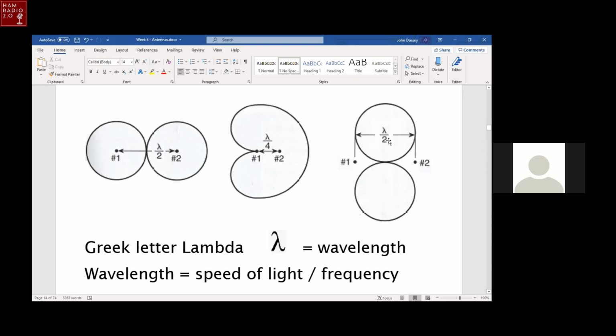That's how you can have a fixed quarter wave vertical array and switch their pattern by changing the phasing of how you feed them. What is the polarization of these? They're all vertical. Yes, they're quarter wave vertical antennas tuned to the same frequency. Hey, John, that's not the same picture that we have in the book. I rotated it.